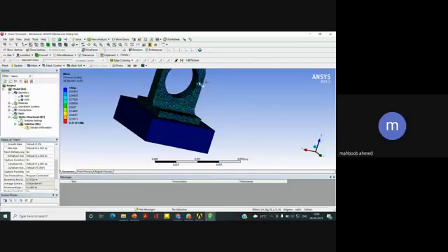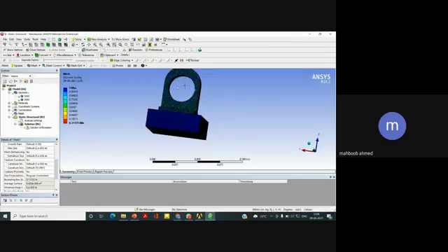So when you are having surfaces or curves very close to each other, not in connection with each other, but very close to each other, then we have to take into consideration the proximity, the closeness of those surfaces or objects while doing the meshing, because that can create an issue. Okay, quality of mesh can be reduced.